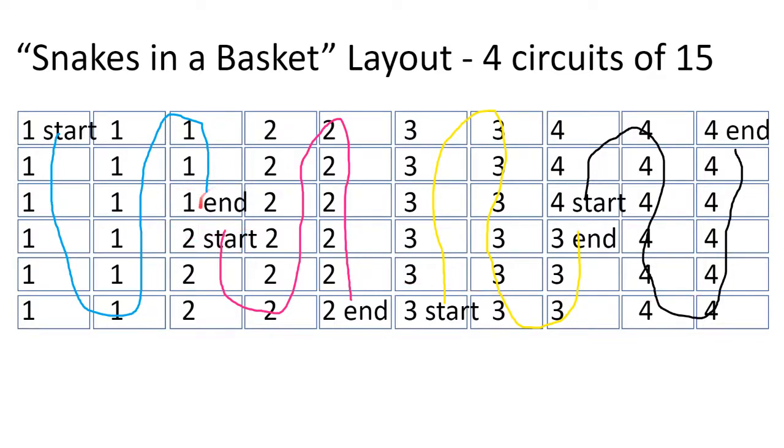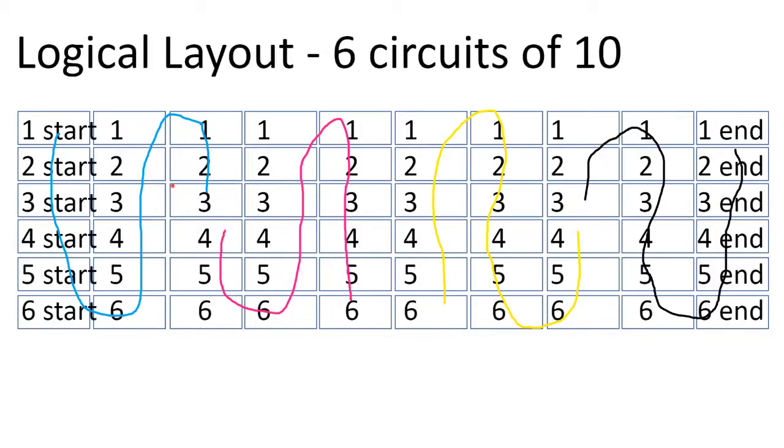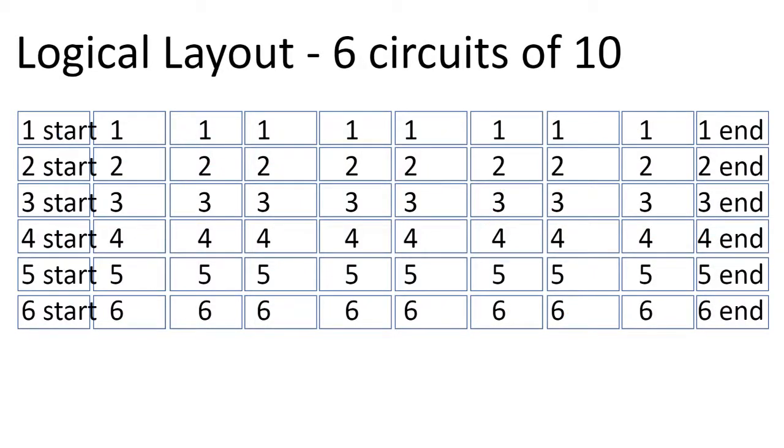But if that circuit map is not available, servicing such an array could become hellacious. So clear, logical circuit layouts keep it simple enough for a field solar installer to visually inspect the array and figure out what's going on with the circuits through visual inspection.